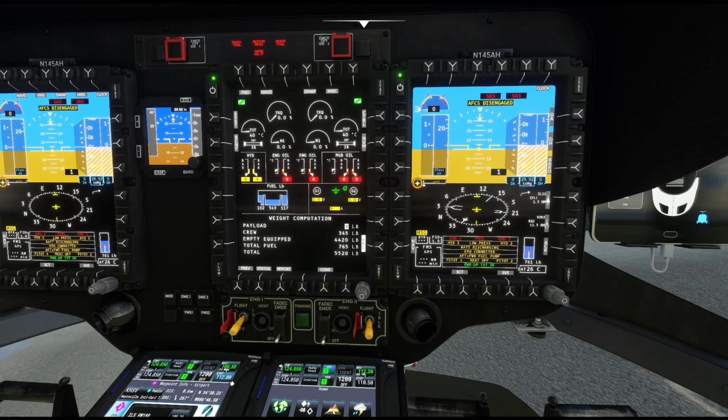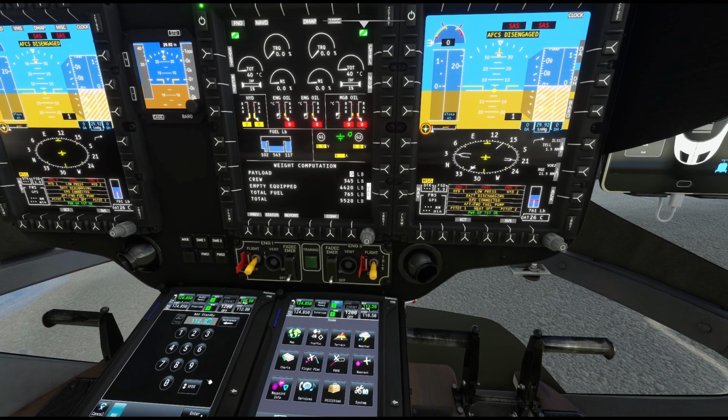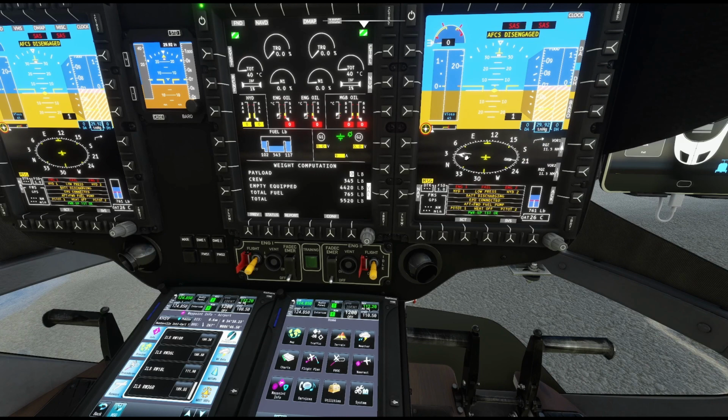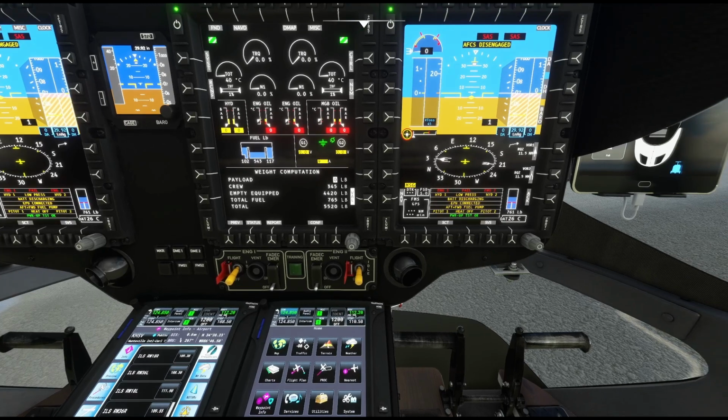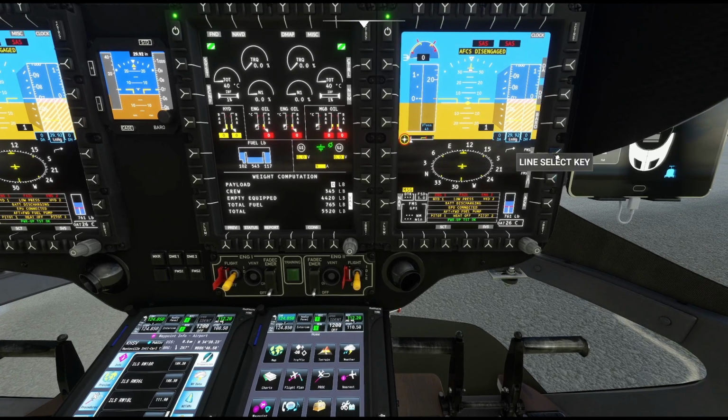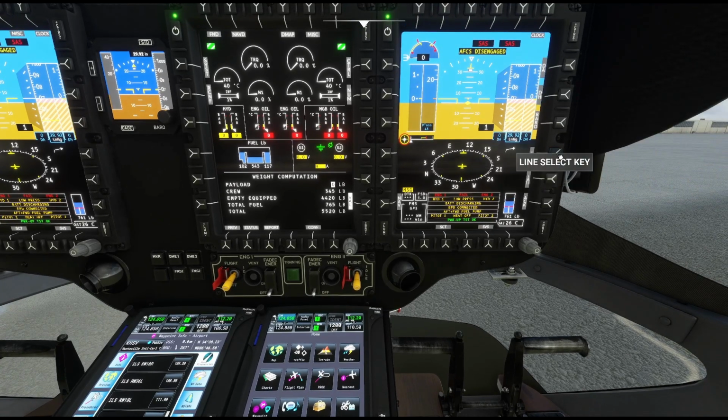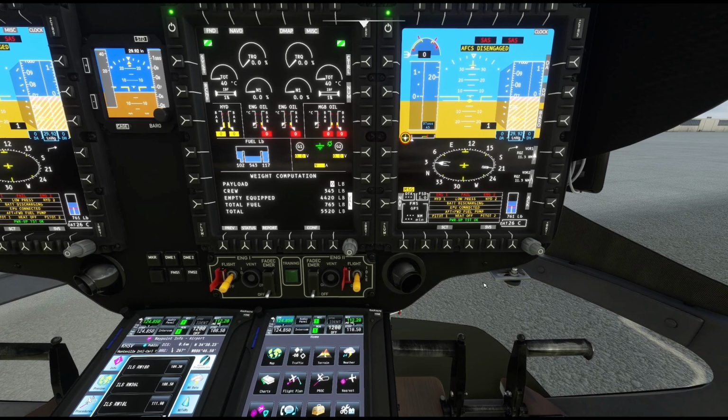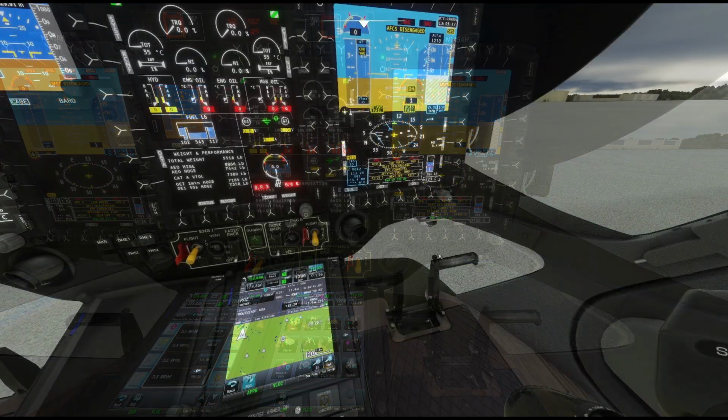You can also use it. So let's go 112.20. We're going to transfer that in. Now we'll see 1 and 2 are both pointing to the same VOR. So we can verify that our VOR is good. We do our 28-day VOR check using this method. We would just have to go in and we would say VOR1, VOR2. They both point to the same spot. VOR check is good. We're at a 0.32 at 11.5 miles. VOR check good. All right.